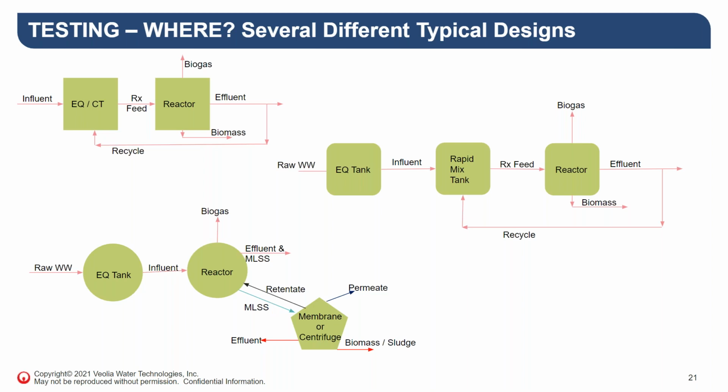The reactor effluent split and went to the sewer or to aerobic polishing, and some of that effluent went back to the equalization conditioning tank as recycle. We kept the level in the equalization conditioning tank at a set point. So as the influent changed, the recycle volume would change because your reactor feed flow was constant.